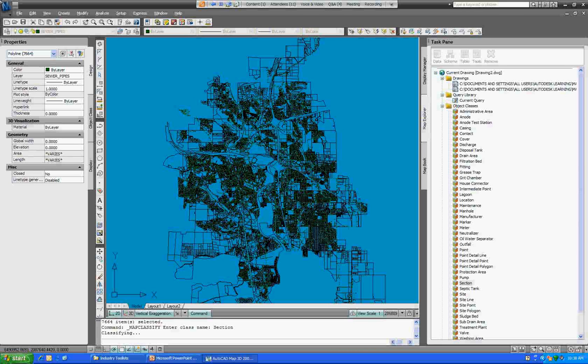And then we can take these to a shapefile and then just to prove the fact that this information does actually go into shape very easily, or into any other GIS format for that matter, I'll connect to that shapefile through FDO and bring it in. We can take a quick look at it.